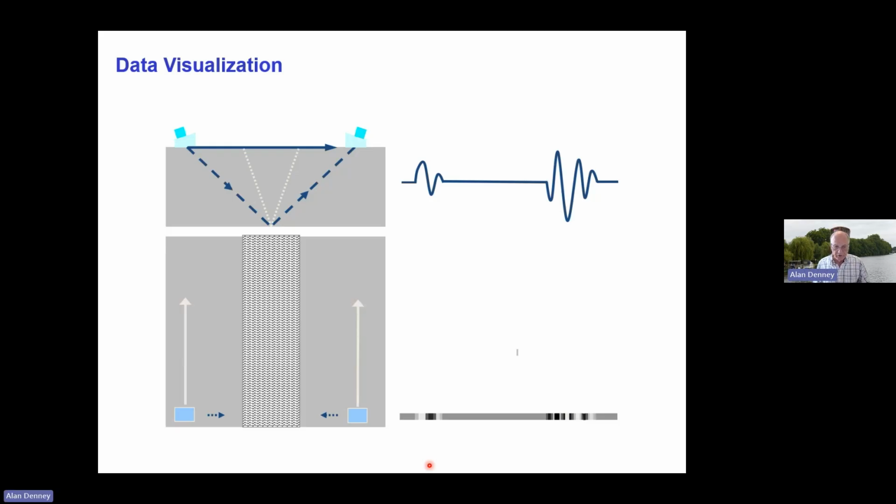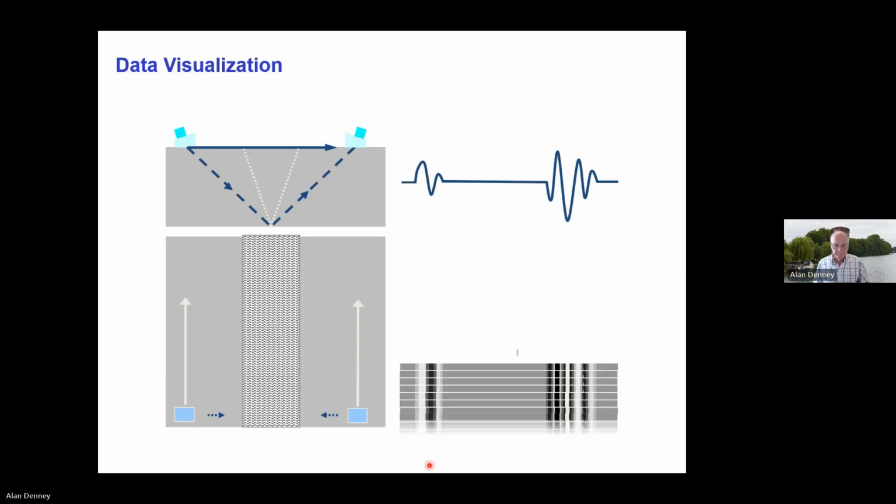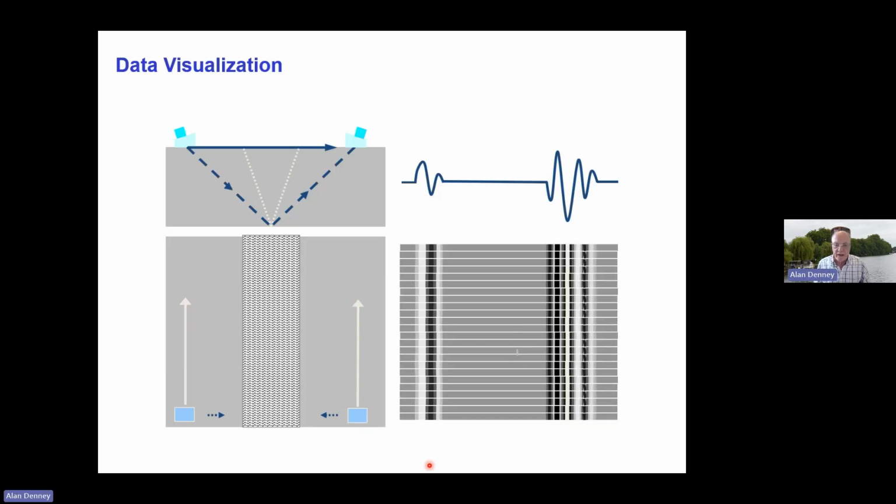So you move those probes and you get that. So you've got the lateral wave and back wall. Now let's introduce a defect. Hope this works. Press again. Yep, we've got our defect there. So now that's giving you the diffraction signals.